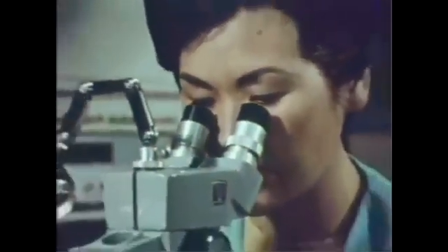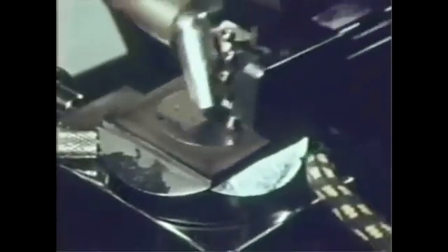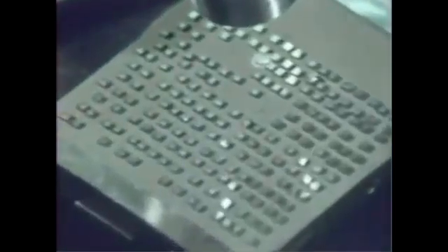Certainly, Harry. Even though we have been very careful in fabricating this wafer containing many hundreds of integrated circuits, not all the circuits on the wafer are flawless. The first job is to determine and mark those circuits which are not good. We test the wafer in a probe testing machine. We then scribe the wafer using a diamond point in the scribing machine. After separating, cleaning, and drying the integrated circuits, we fish out the ones that are bad. If we have been successful to this point, we have a high yield of good ones.